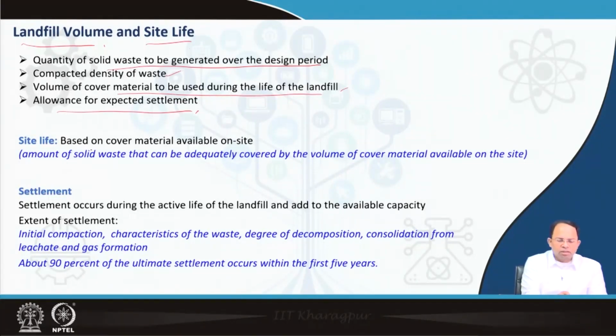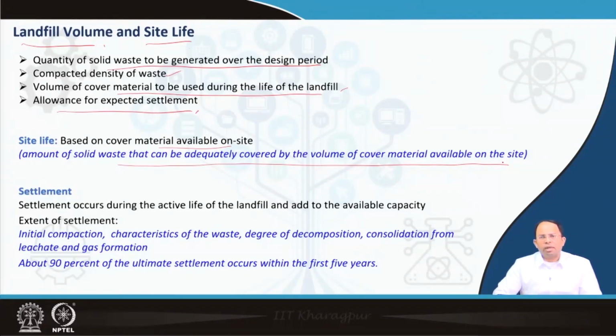The site life is based on the volume of cover material or soil, or the amount of solid waste that can be adequately covered by the volume of cover material available on the site. So, this could be one of the criteria for determining the site life of that particular landfill site.